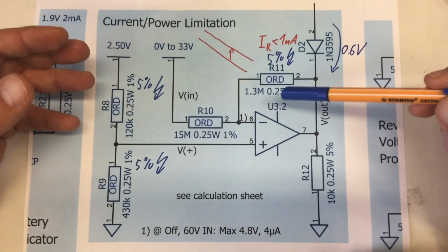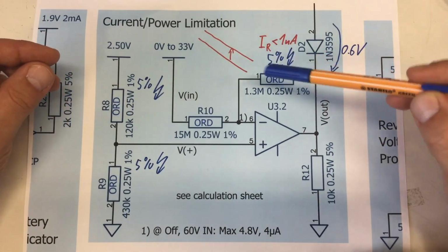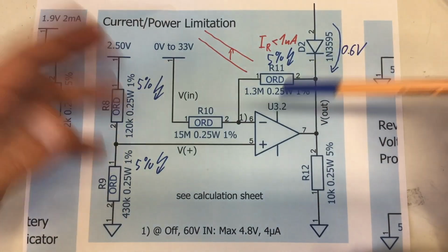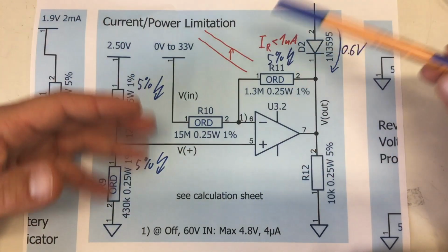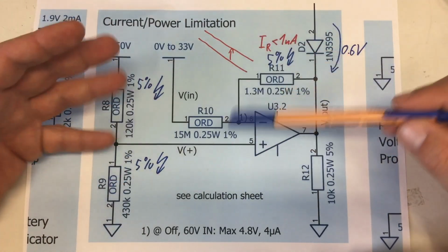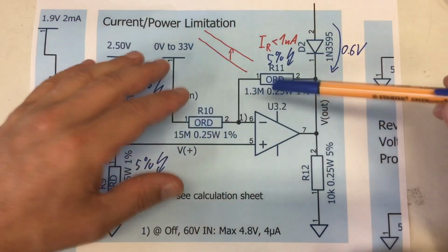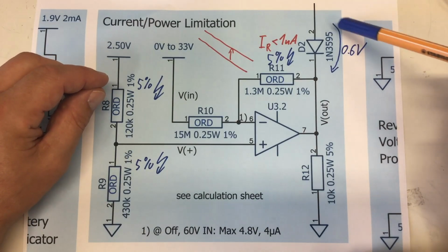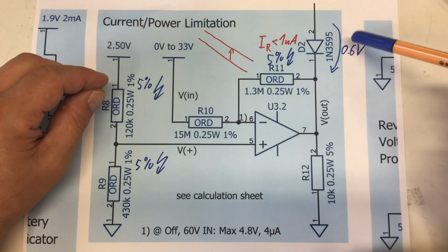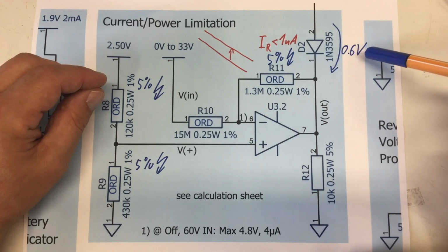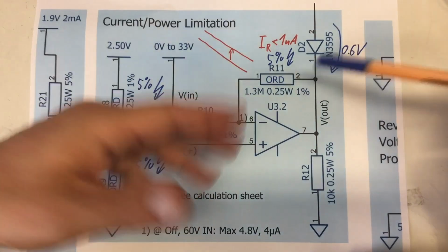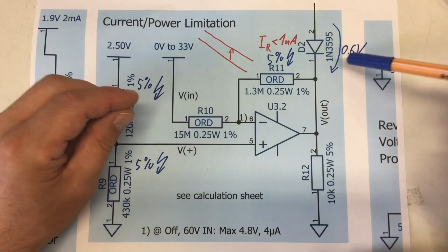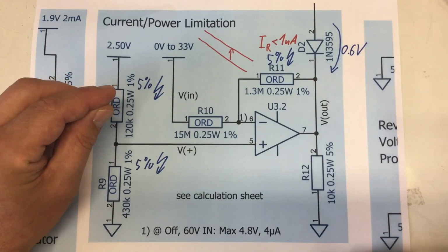I built up the whole circuit mostly with 5% resistors instead of the 1% I want to use, so there is of course a little variation there, in that order of magnitude. But another assumption I made was the voltage drop across the diode being 0.6 volts. That's the value you normally use for a diode. Maybe we should measure that.